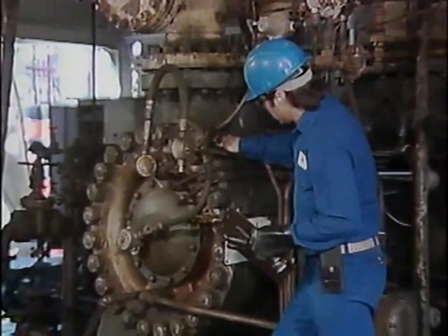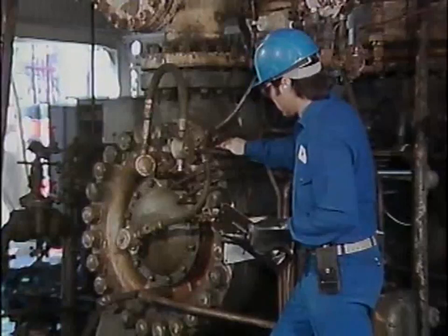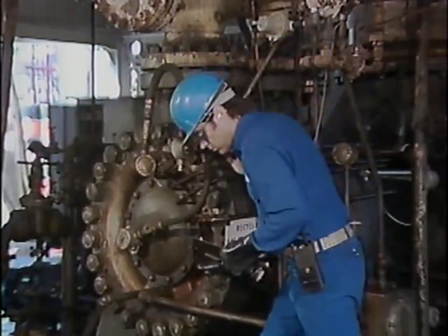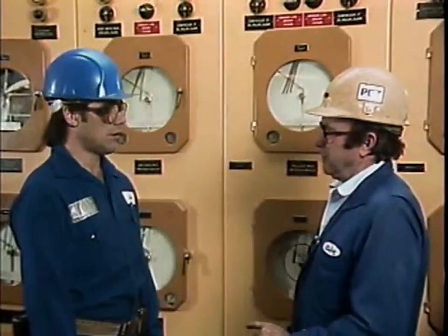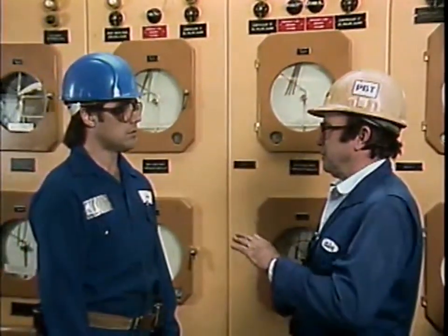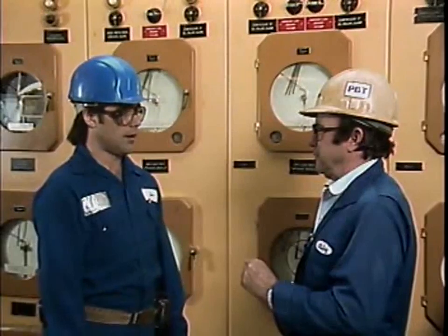Most centrifugal and axial compressors operate at very high speeds, usually several thousand revolutions per minute. So they must be started up and operated properly, or they can be severely damaged. A compressor startup consists of a series of steps. These include preparing the compressor for startup, warming up the compressor, and starting the gas flow to the compressor. The warm-up is continued as the compressor is brought up to operating speed. In our example, the compressor is used to compress a gas that is supplied from storage tanks. Many compressor startups are performed by more than one operator, so good communications are essential.